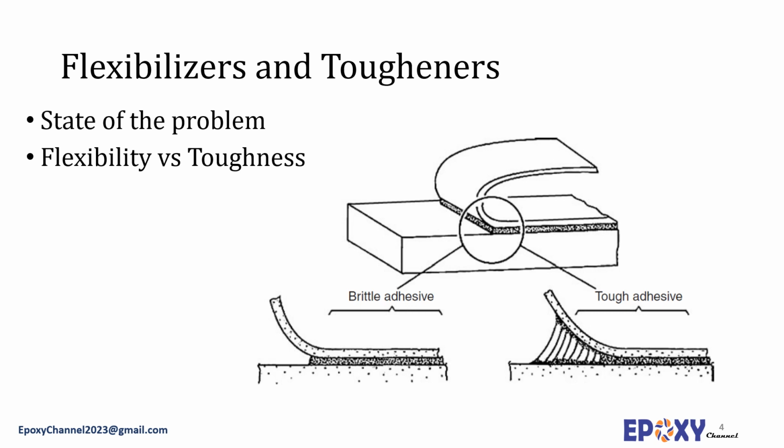Toughness, on the other hand, is characterized by a material having both high elongation and tensile strength, whereas flexibilizers work by deforming. Tougheners improve properties because elastomeric inclusions in the epoxy matrix absorb energy and stop a crack from propagating.